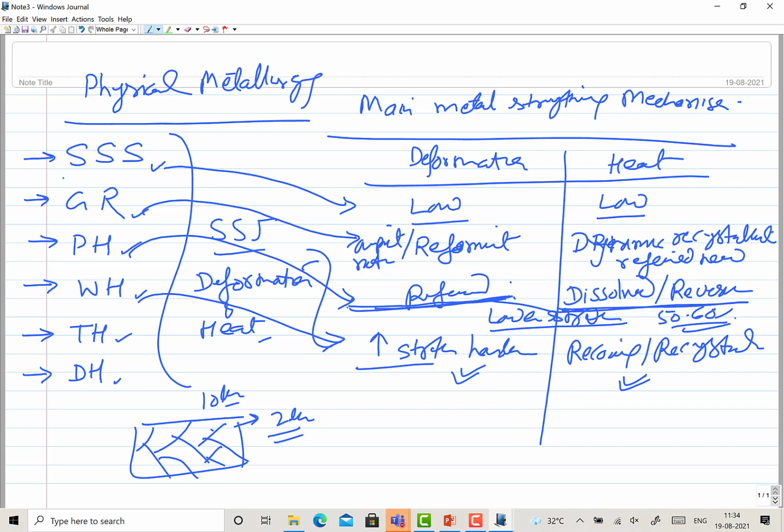Okay, so deformation will be facilitating the increase of strength. On the other hand, heat will be compromising. So if you can realize the deformation without inducing much heat, or by controlling the rise of temperature through external forced cooling, then it's good. You can improve the strength.